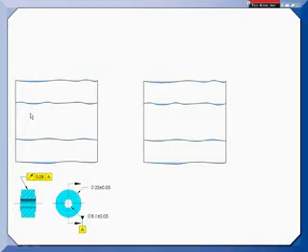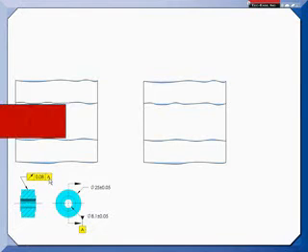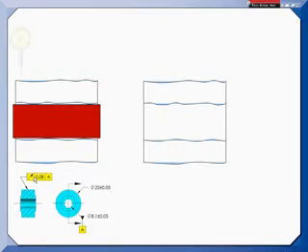Well, first we fill A, regardless of its material boundary, so maybe with the biggest pin that'll fit in here. And then to check the runout, I'm going to check slices all the way along here. I'll be looking at different slices because it's circular runout, and the slices will be the circular slices. I don't want to mislead you by showing this going back and forth like that. So I'll check this slice, I'll rotate the part, then I'll go to another slice. So I'm looking at the variation in the surface of the roller. That'll help me understand what will happen in the assembly.